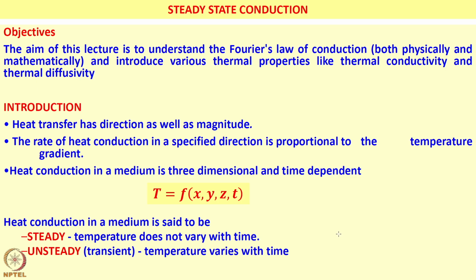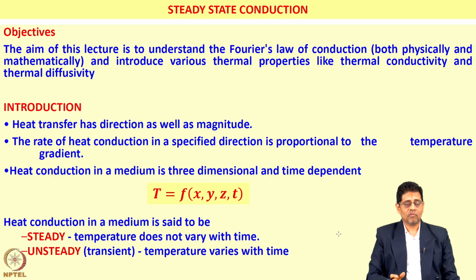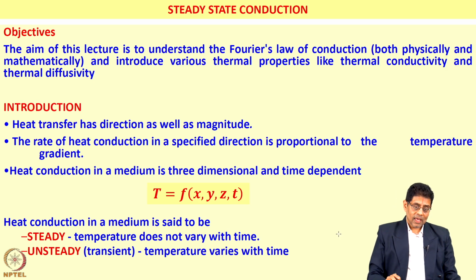Okay. So, where are we going with all this? Now, we are going to start focusing on steady state conduction. Conduction essentially is, as we said, molecular transport of energy and of heat, and we want to see how 1D conduction, that is conduction which is only going to be in a single direction, either x or y or z, or in case of radial system along the radial direction, how to formulate the problems, how to solve for temperature distribution. Why? Because in heat transfer it is important that we get the temperature of the region or location of interest.